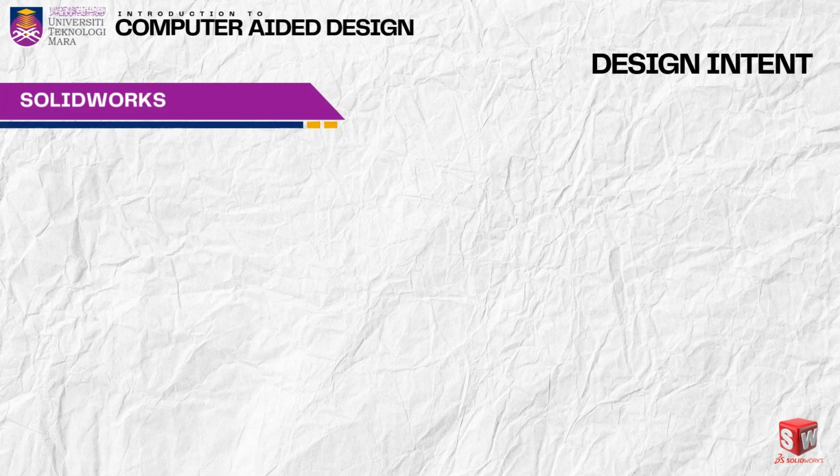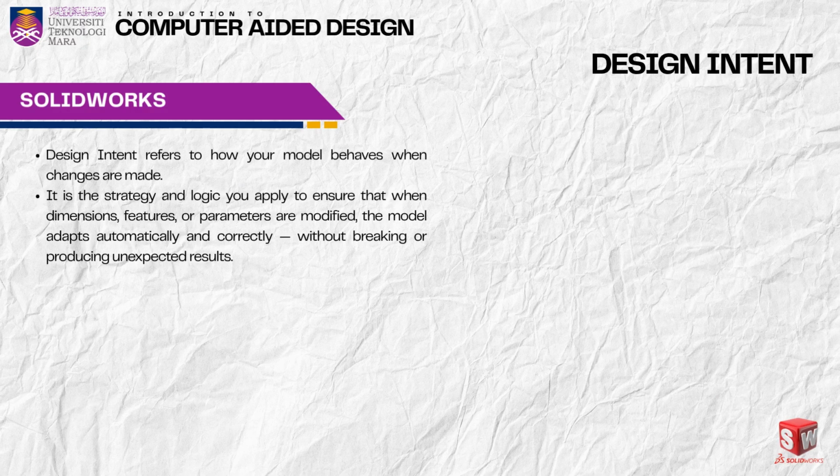Now let's talk about one of the most critical concepts in CAD modeling, which is design intent. Design intent refers to the strategy and logic you build into your model that determines how it should behave when changes are made. It's not just about drawing a shape, it's about teaching your model how to think and respond. When you modify dimensions, move features, or adjust parameters, a model with well-defined design intent will adapt automatically and correctly, without breaking or producing unexpected results.